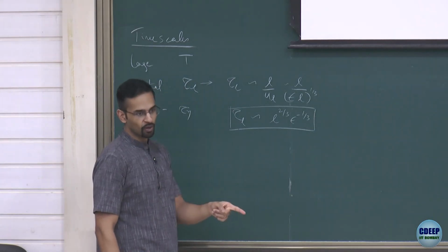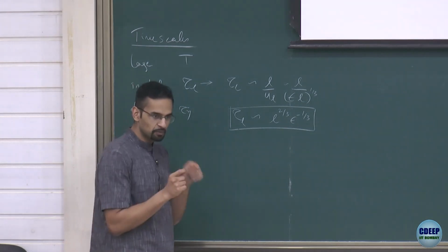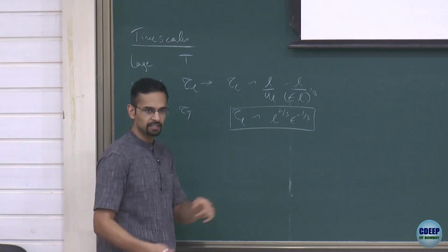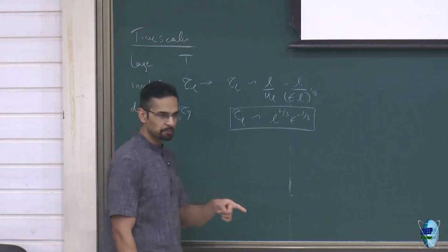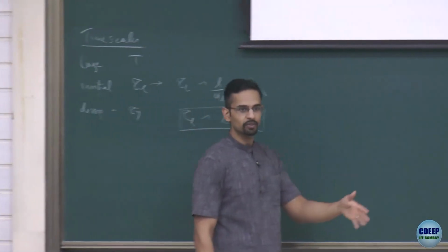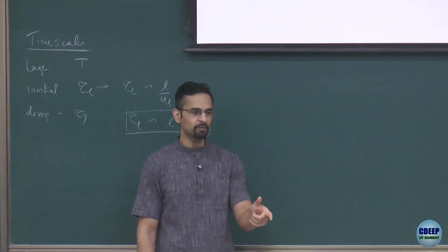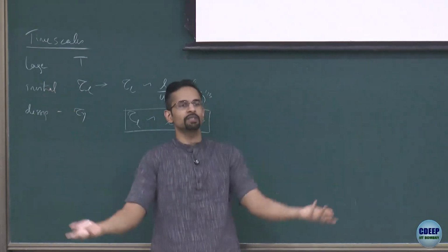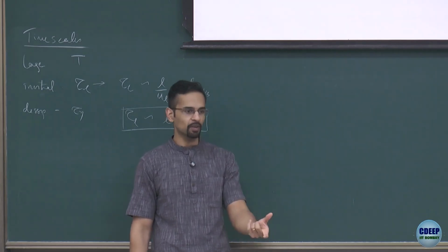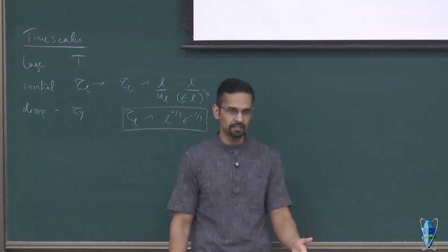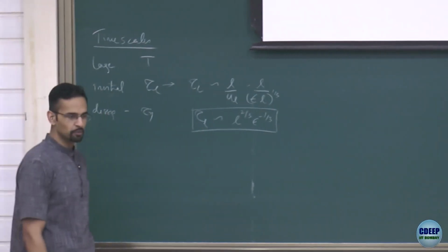And if I look at long time intervals, I will sample the differences of the big eddies. If I take small time intervals, the big eddies will hardly change. It's the small eddies that will give me the temporal response. So just by looking at the power spectra at a fixed point, I will also realize that there are different kinds of eddies in the flow. Okay, because if I take a small time difference and I just have one big eddy, almost nothing will change. If there are fluctuations even at small time differences, it's because there are small structures there which are changing rapidly. Right? So by doing a Fourier transform in time, I'll also get the same information.